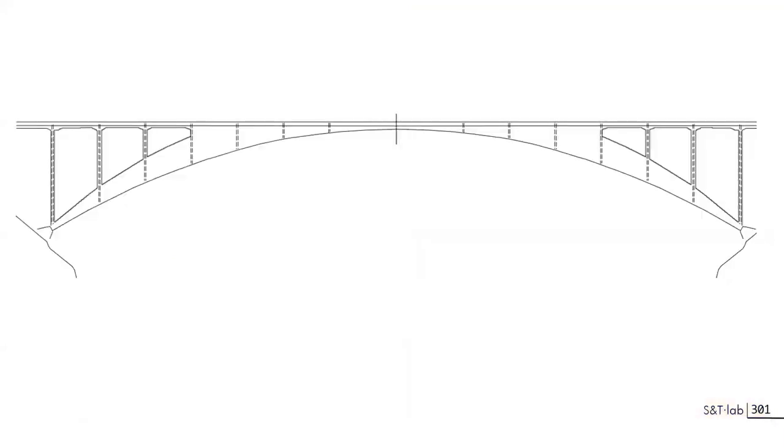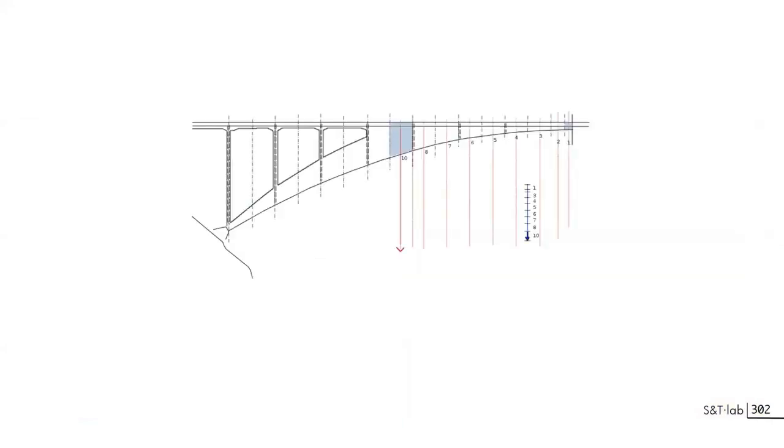So this is the bridge that you know already, and we will look first at analysis; I will discuss design just after. For analysis purposes, I will slice this bridge and calculate the corresponding loading of each of these slices and start building a load line.